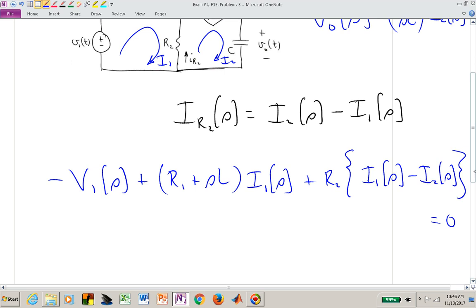That's now going to be in the other direction in terms of voltage drop across R sub 2. So now I have R sub 2 times, and if you'll humor me, I'm going to just not include the argument S in my I sub 1 and I sub 2. This is R sub 2, and now I've already made the mistake, but this is now, I want the drop from plus to minus going from bottom to top, so I now need my net current going up is I sub 2 minus I sub 1.